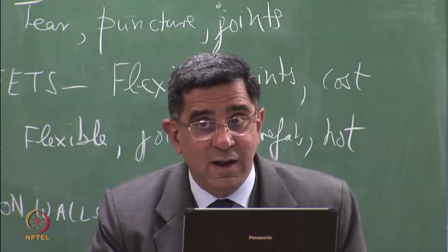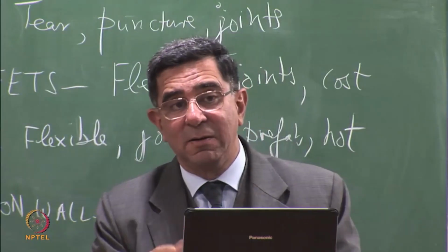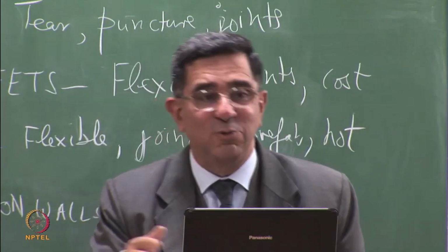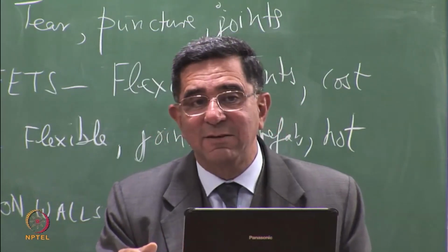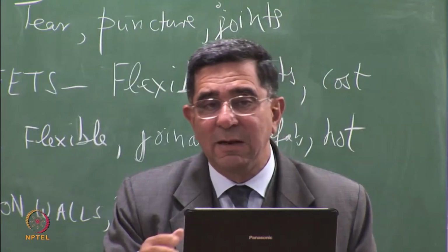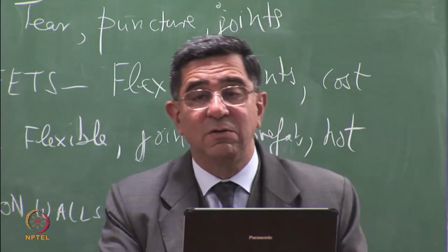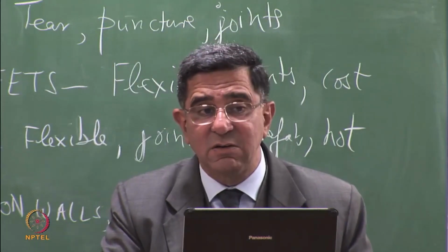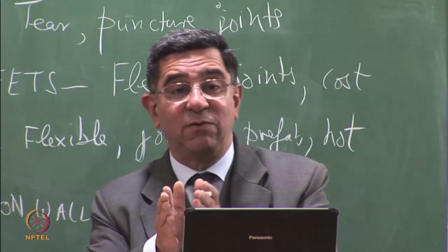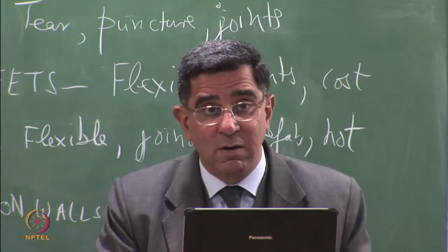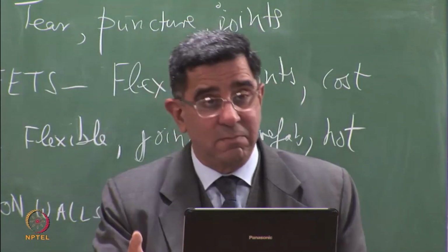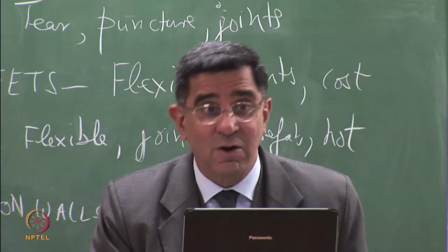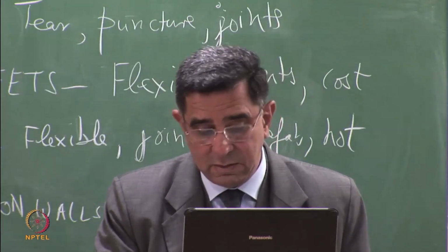They are self-healing. If you take a clay which has shrunk and you give it water, what will happen? If it can shrink, it can swell. So these shrinkage cracks do close themselves, and therefore they are reversible. This is important because one of the great negative aspects highlighted in clays is shrinkage cracks. And you feel, oh yeah, this crack is 5 millimeter wide, all the water will go down. But the fact is, every time a lake or pond dries up and rains come again, all the water doesn't go down because the cracks heal. So they have a self-healing capacity.